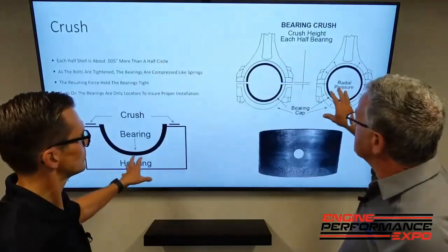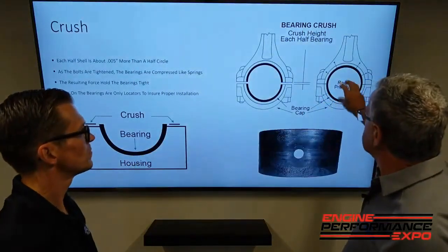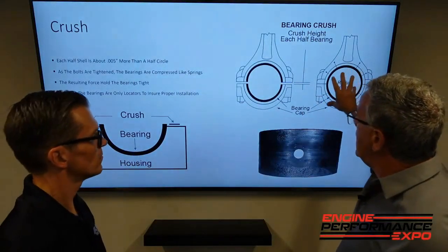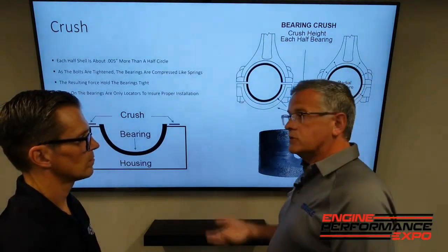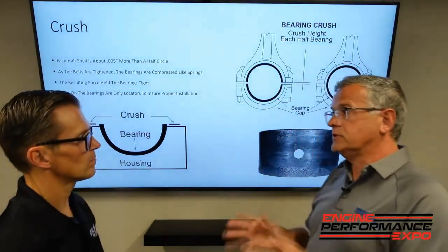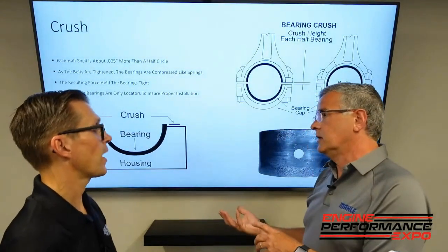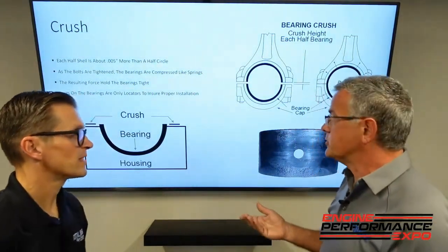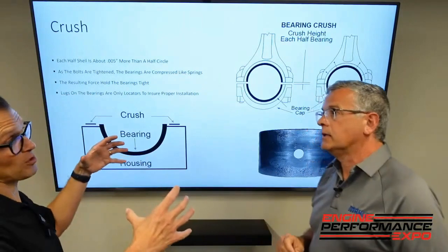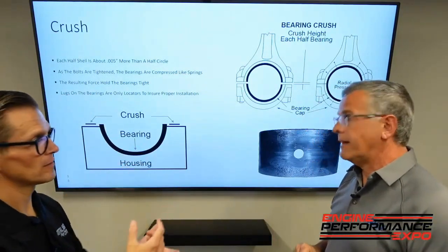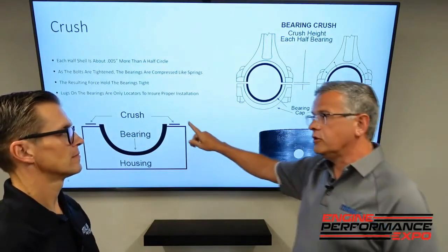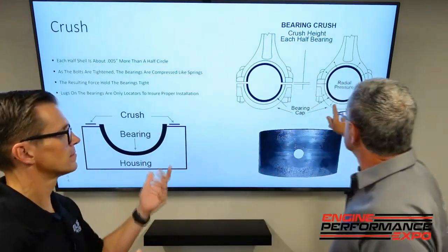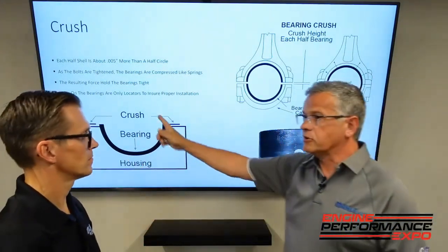So there you go. As it's saying, the radial pressure holds the bearing in place. The one thing we have found is that on typical applications, if a guy takes steel connecting rods and puts aluminum in, there's more thermal growth. So yes, the aluminum is going to grow. The housing bore is going to get larger during operation. Absolutely, so it's going to lose some crush. At that point, you can have a bearing that loses the radial pressure and the bearing starts to spin.